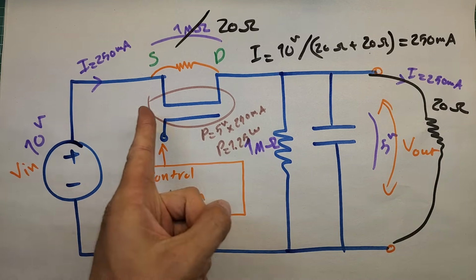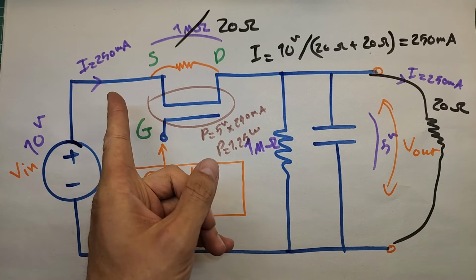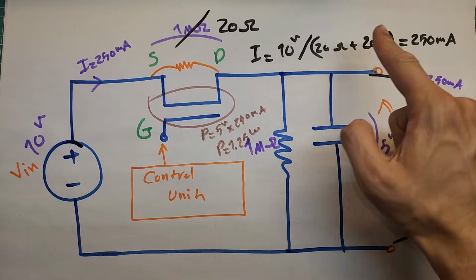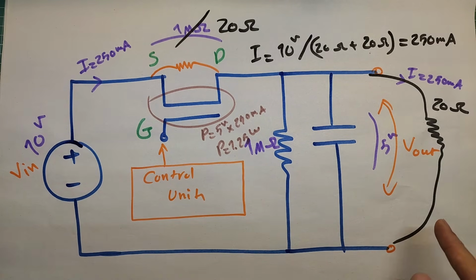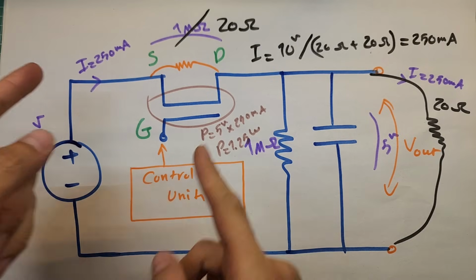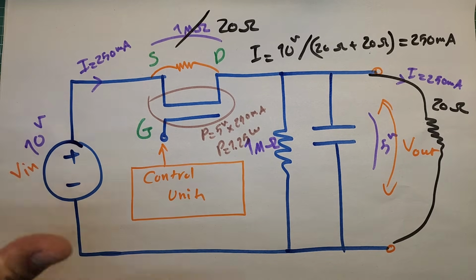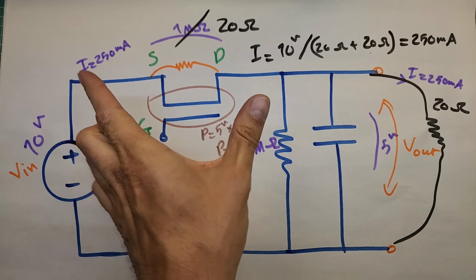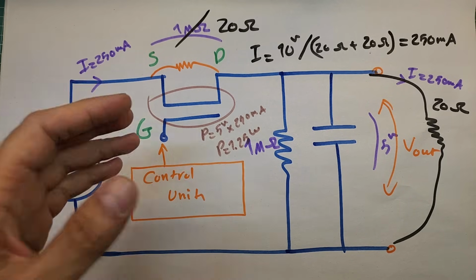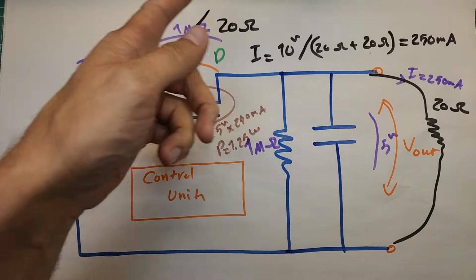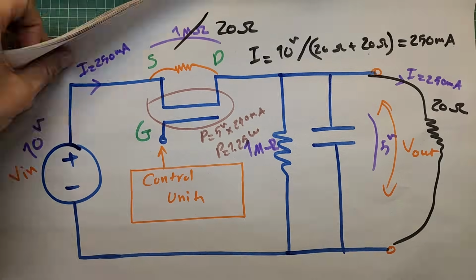Look, the power dissipated here is calculated by multiplying the current drawn by the load and the voltage dropped across this resistor. The higher the input voltage, the higher the voltage dropped across this resistor, and consequently, the higher the power dissipated on this resistor inside the regulator.